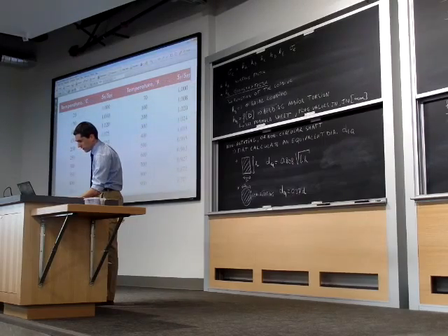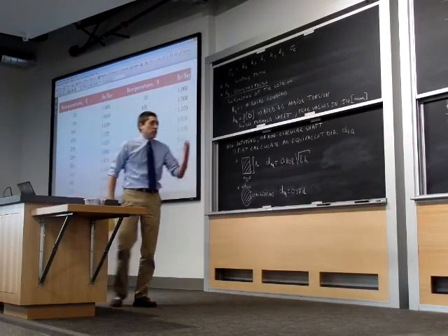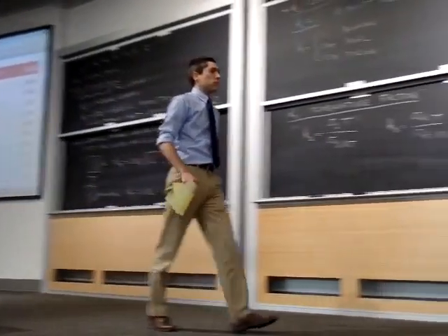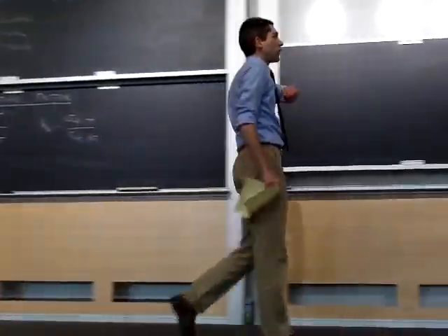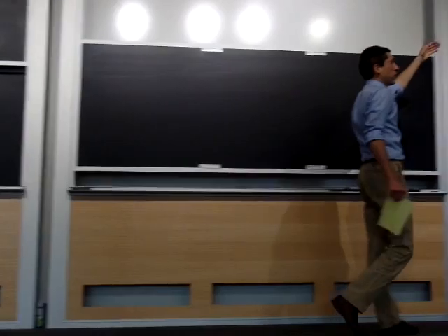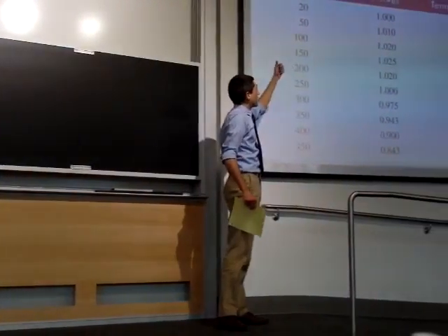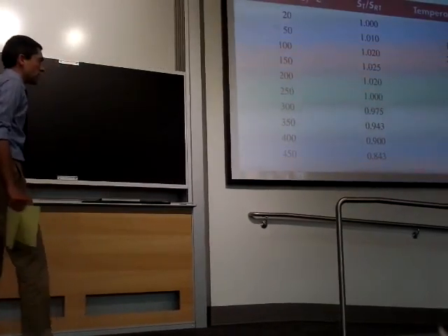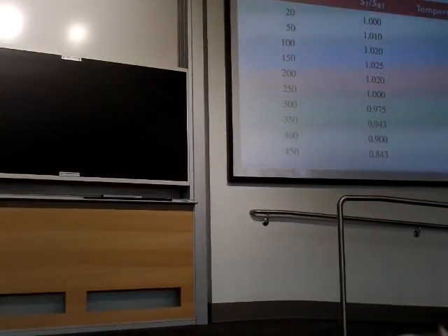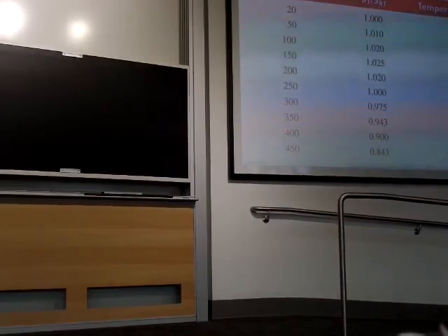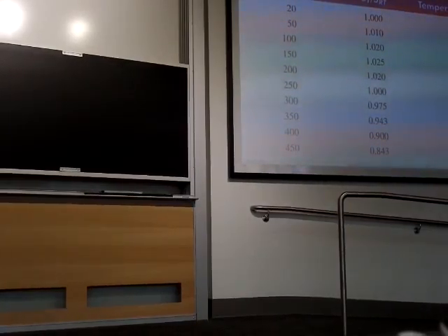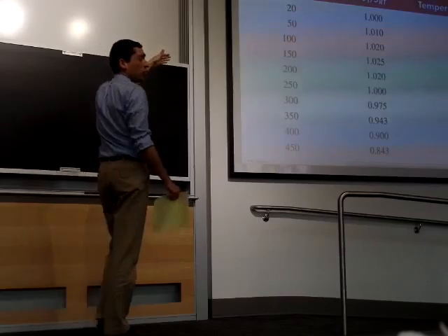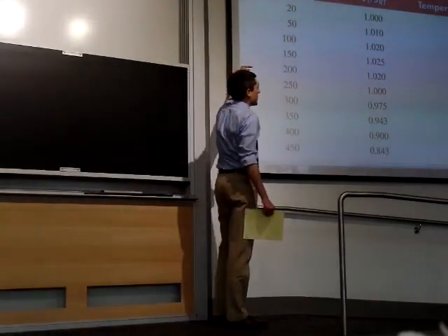Right? And so look at the column in Celsius. So at room temperature, 20 degrees C, St over SRT, the strength at the temperature that you're evaluating, which is room temperature, divided by the strength at room temperature, is of course 1. And then as you increase your temperature, actually you see that your Kd factor can even be a little bit higher than 1.